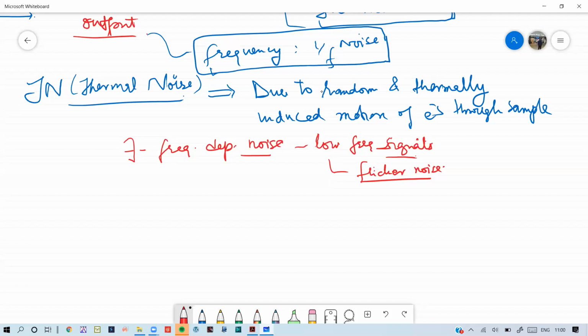What we use are sensors which have very low impedance, that means very low resistance and very low scattering, so there is not much scattering or random motion of the charge carriers, which can create a large resistance or large impedance in the circuit. So low impedance circuits are used so that we can measure small signals by avoiding that thermal noise.